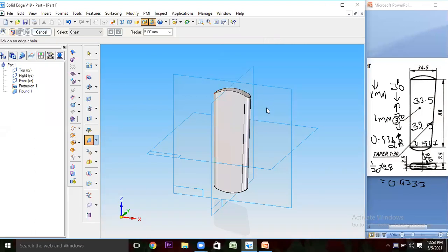For that purpose, I cannot create it directly. If I go over here, there is a cut, a radius of 60 mm cut, and that has to be cut on this particular section only, from this particular region, not the entire Cotter, only at the tip of this Cotter. So over here it should be done, and below also it should be done.